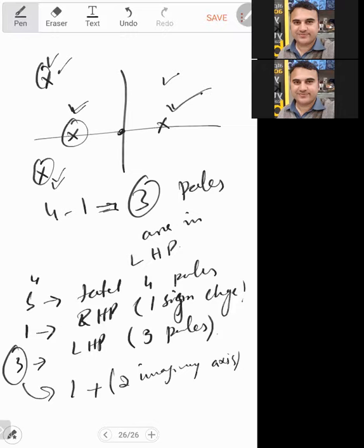We have to find the differentiation of that, replace the 0 row with the coefficients of the differentiation of the auxiliary polynomial, and continue. But the auxiliary polynomial will introduce what? This will introduce the symmetrical and the imaginary poles.